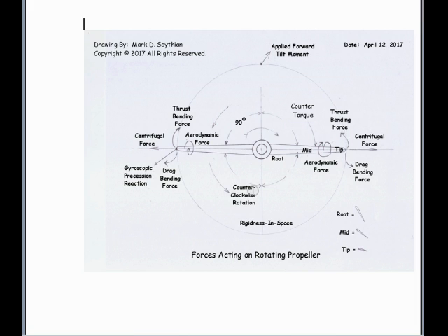Last but very important application to cover, knowing the forces and moments on a rotating wing or a propeller, is the application of counter or contra-rotating propellers. And like with drones, they will electrically control the RPM to be equal and opposite through computer controls and electronic speed control. But with something larger like an actual airplane that has counter-rotating propellers, you're always going to have a gas engine, and it's kind of hard to individually control every engine's RPM equal and opposite. You need to have an equal and opposite counter-rotation of the propeller to take advantage of counter or contra-rotating propeller application.